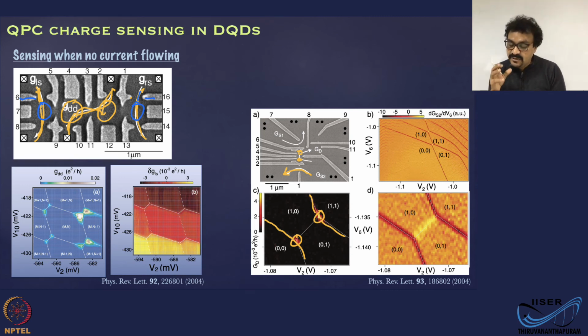And it is telling you a lot more information than the direct current measurement of the system. So the charge sensor in this way is a lot more superior to the current measuring technique whenever it comes to nanoscale devices where the current levels are really, really low. Okay.